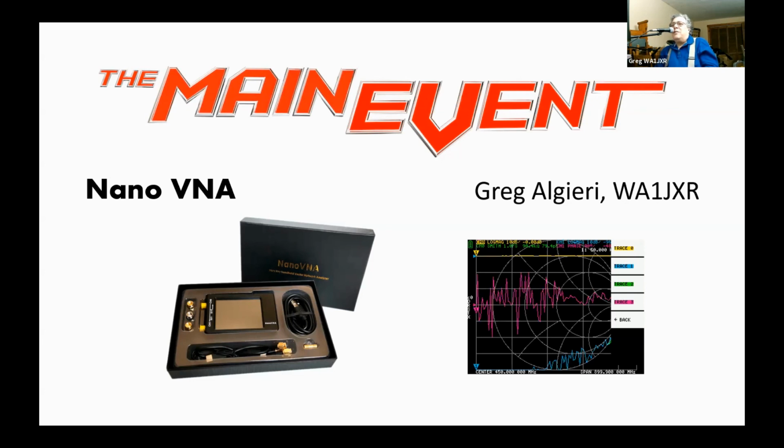When I was at work and we were measuring sensitive microwave components, we couldn't do that. We had to measure in whatever reference plane the connector type for the device under test was. So we had multiple cal kits of all different connector types and waveguides and all kinds of stuff.